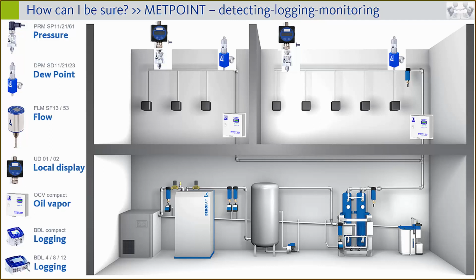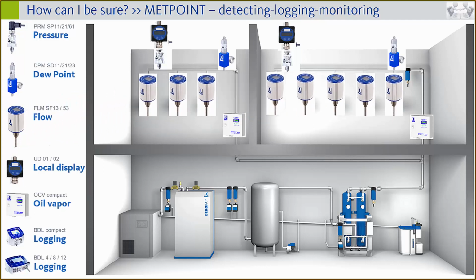And these costs should be separated for each application. So all applications would get a flow meter integrated. For the customer, it is easy to detect the costs for his application which are created by the compressed air consumption.